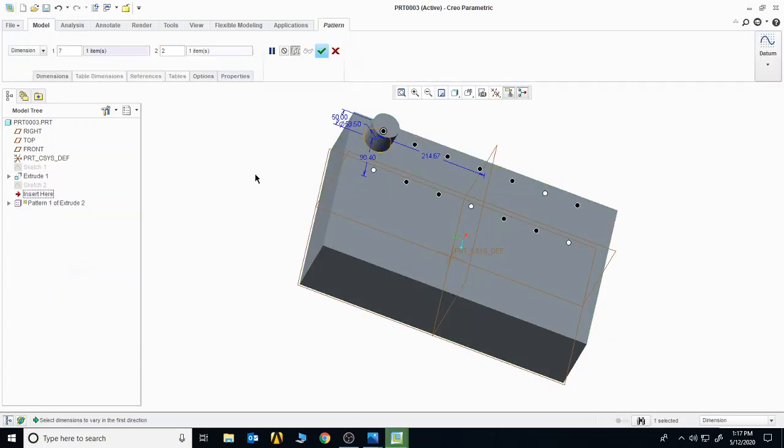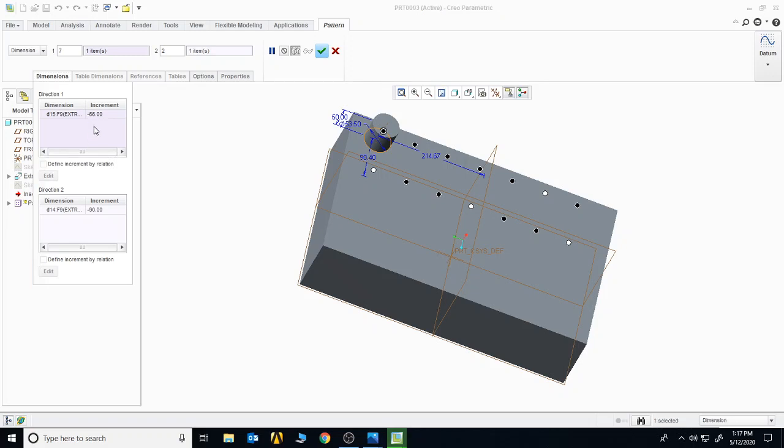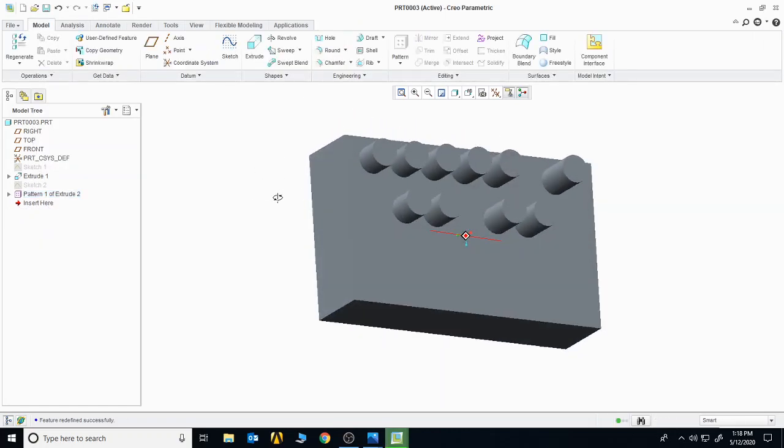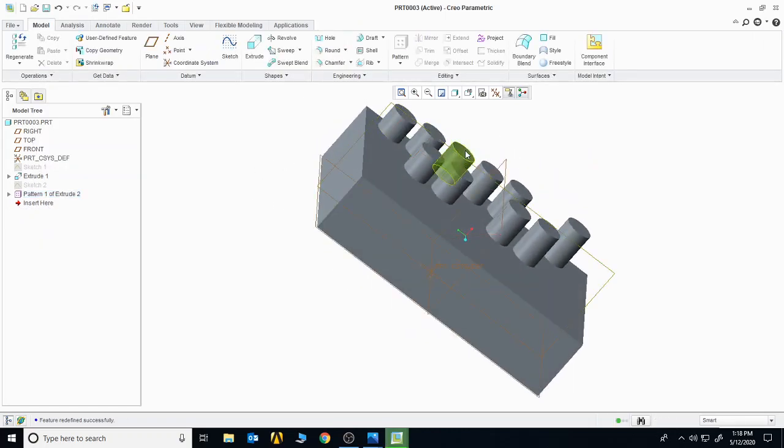Again, edit definition, go into the dimensions, right click here, press the control button, click on the height here. It will get generated here, add it, and if you want the size of each cylinder to be 5 inches higher than the previous one, so enter 5 here. Click on OK. Once you click on OK, you can see the height of every next cylinder is slightly higher than the previous cylinder, and that is at an increment of 5.